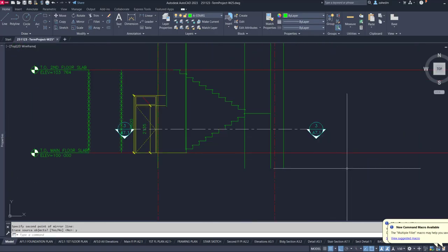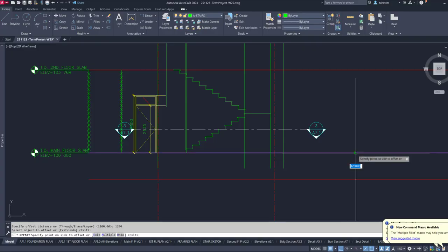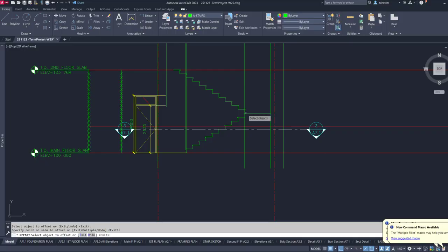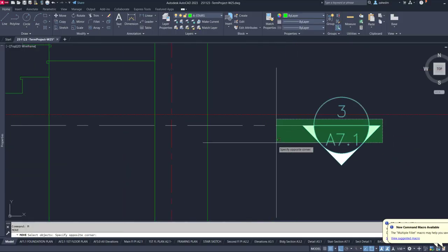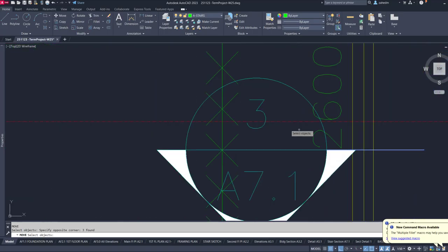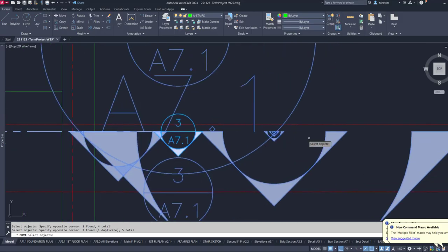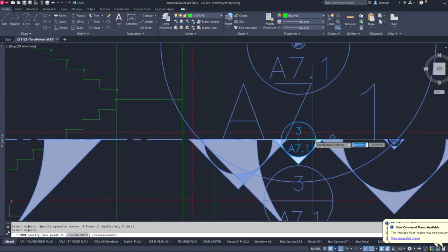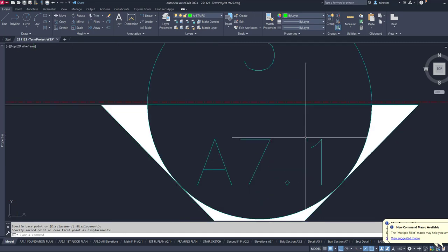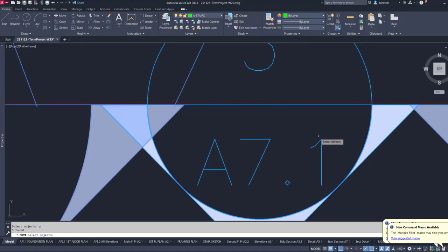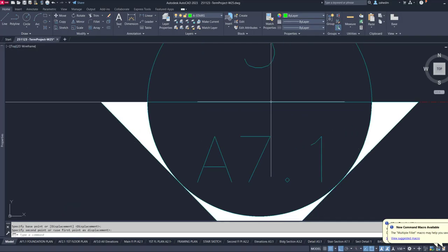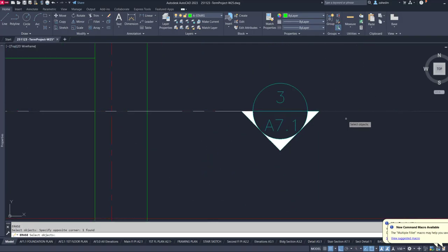Let's see, this red line, I'm going to offset that 1200, which is equal to 4 foot, and bang, I'm going to move this cut line to be at that 4 foot. No one does that technically in the realm of drafting, but I would like to basically reconfirm the concept for everyone. If I move the previous object from this line to that line, it's now exactly 1200, okay?